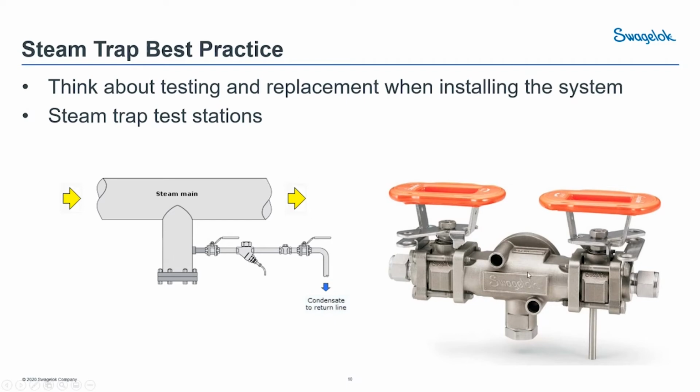One product that we have here are these steam trap test stations. They're pretty popular because that whole process is integral into this nice compact body. So you actually attach your steam trap to the other side of this flange here. It's a standard flange. It has the filter integrated in the bottom right there. What this also does is this is a ported ball valve, so you can close this downstream line and it actually opens up the trap itself to this tube going out of the bottom. So what that does, if you leave the inlet side open, it allows you to do a visual test on your steam trap right there on site.